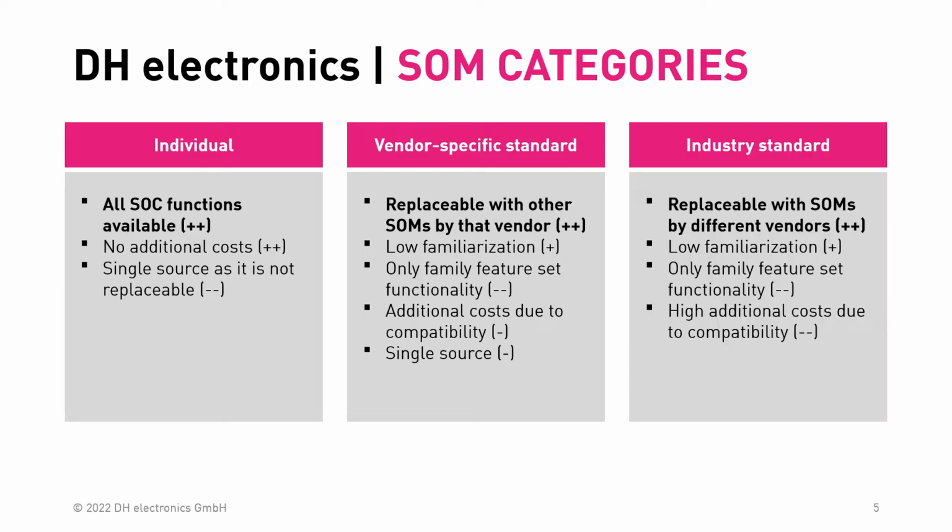The last category, the industry standard. So here the big plus is replaceability by SOMs by different vendors. So this is, I think, the big plus here. Again, the low familiarization time. Again, only the family feature set of this specific standard is available outside on your mainboard. And typically we have high additional costs due to compatibility with this standard.